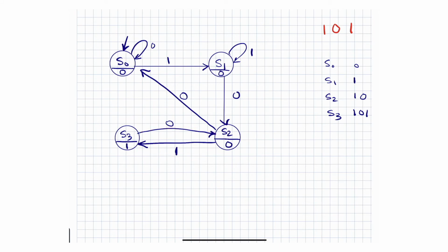What if you get a 1? So it's a 1 followed by a 1 followed by 1. I think you can go in here, because this is actually the 1 in here. And I think that now completes the whole state diagram. All right, so I have the Moore state diagram at this point.